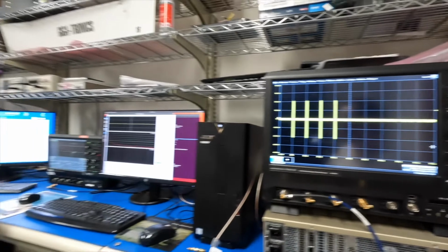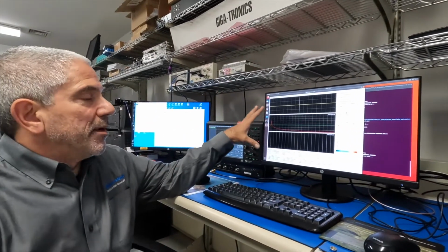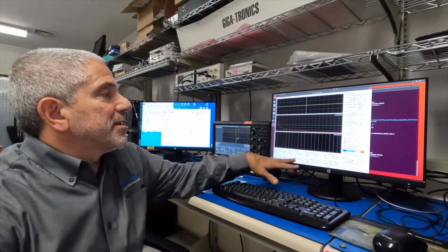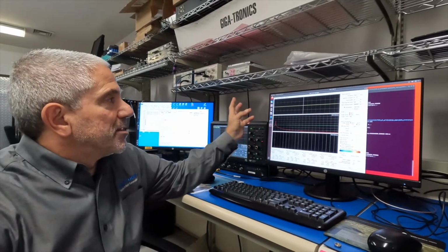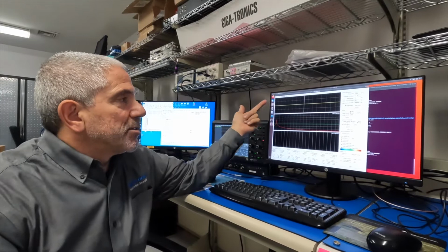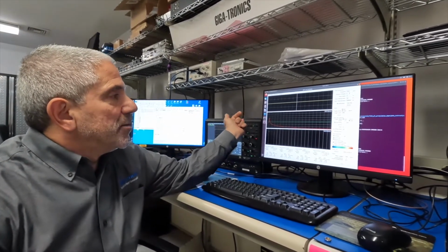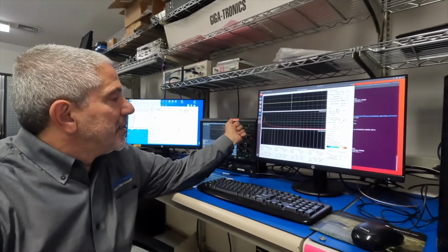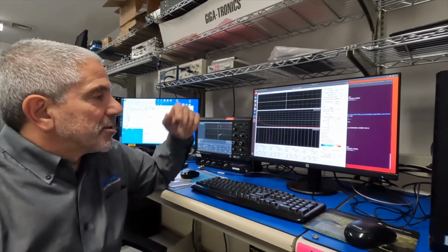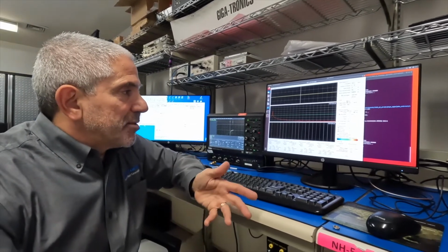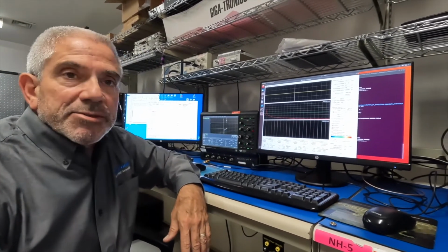And we do that through a GUI that allows us to show the results of all the pulses processed in near real time with 3 displays. Time domain display, which is just voltage or amplitude versus time. A frequency display, which is frequency versus amplitude. And then a rolling histogram or a spectrogram of frequency versus amplitude in color, and also a time history of that.